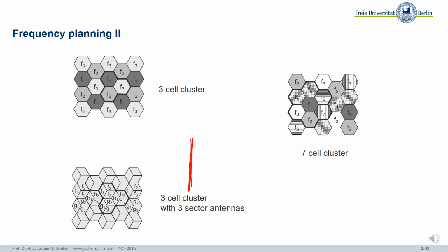You see this antenna pole, and you see these slightly tilted 3 antennas, each with 120 degrees, covering then the 360 degrees, the main lobe of this antenna slightly downward towards the road. That's just one example with the sector antennas. And there you have to do all the cell planning. That's exactly what the mobile phone operators do, all the cell planning.